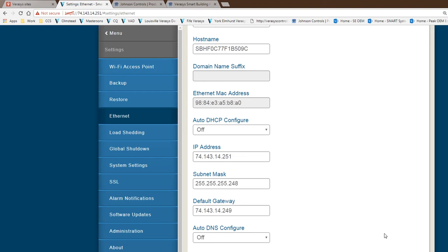Probably the best thing to do after you save it is another reset, and let it come up. What you should be seeing after it comes up is the Ethernet light blinking away. The way you can test this is to pull up your phone, your iPad, or the computer, and hit the IP address that's been provided to you to be able to get to the network.